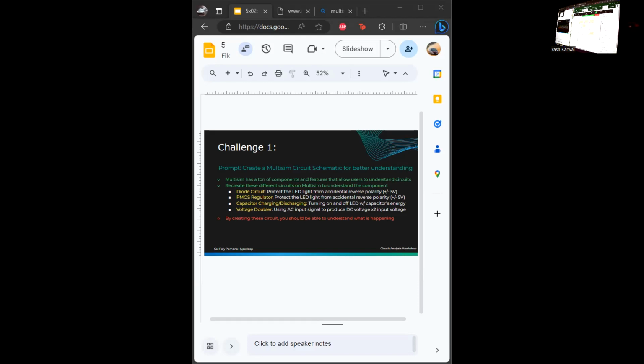It's not far, yeah. Okay, so a PMOS is this. So PMOS, how it works is this is the gate. Right? Drain, or so this is the official name of this. Source, drain, and gate, right? And so when you are putting in to get the voltage or the current to go through here, this gate has to be the least voltage.